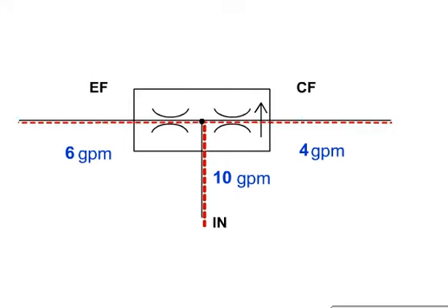All input flow first goes to meet the required flow of the controlled flow circuit. Flow will remain constant through the controlled flow port as long as it is at least equal to or more than the controlled flow setting. Any extra flow will exit the excess flow port and can be used in another circuit.